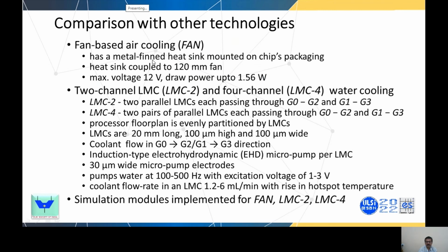So this work has been compared with the fan-based air cooling and liquid continuous flow, liquid microchannel cooling with 2 channels and 4 channels. So the microchannels, you have the continuous flow, and the flow takes place with the help of an induction type electrohydrodynamic micropump in each liquid microchannel.